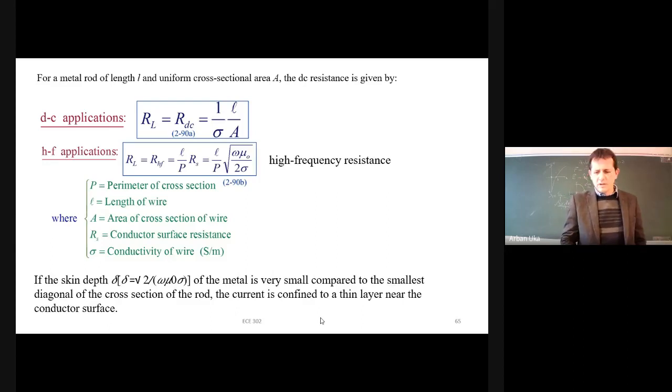We remember this from the electromagnetic wave discussion, when we had the reflection from a conductor or from an insulator. As a reminder, any component which has a non-zero conductivity has a certain skin depth, because the wave intensity is attenuated very fast, since the conductivity induces an attenuation constant alpha, and this also happens in these components of the antenna.